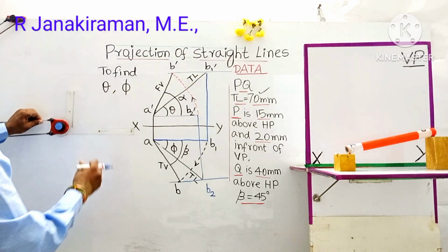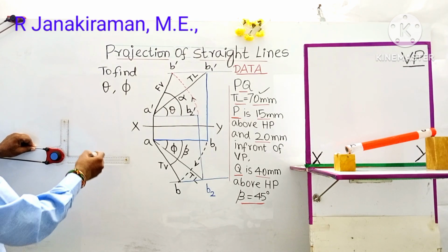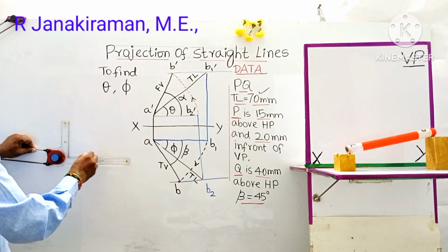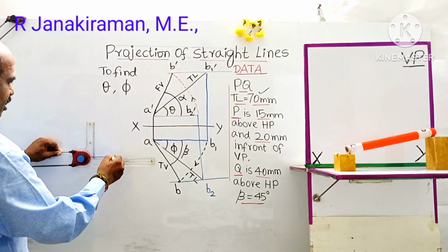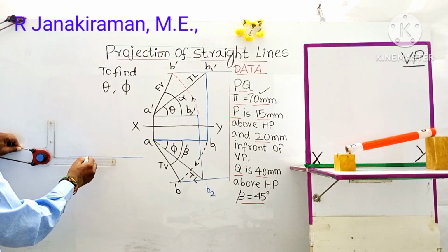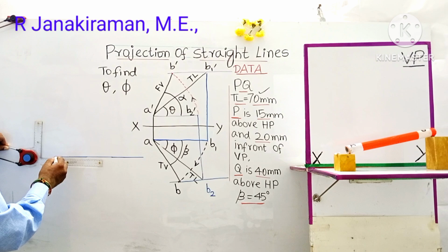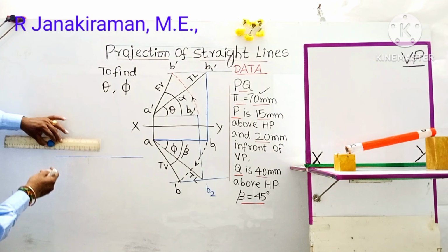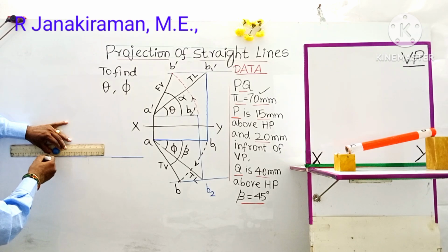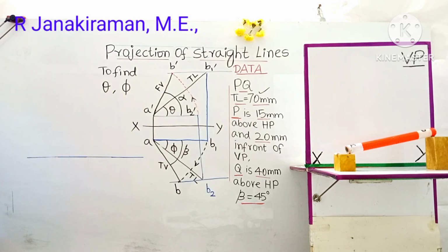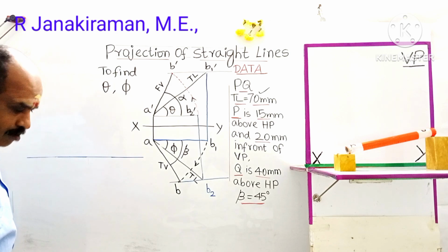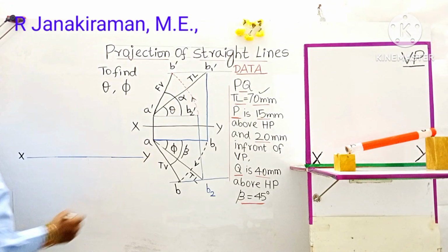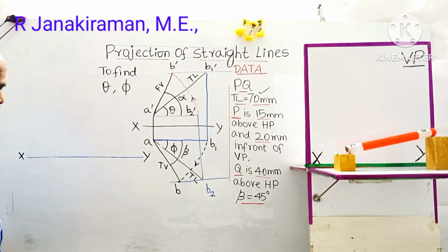Okay, using the longer scale, draw XY line called the reference line, using the longer scale of a drafter. Understand? So these lines shall be drawn by using a 2H pencil or H pencil. It acts as the reference line. That is, this is the XY line. Mark the X and Y. Writing work shall be done by HB pencil or H pencil, so that it appears dark.